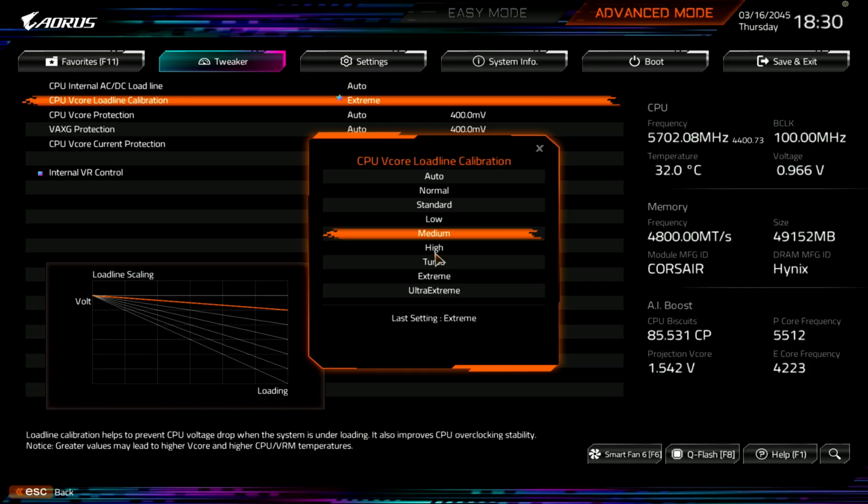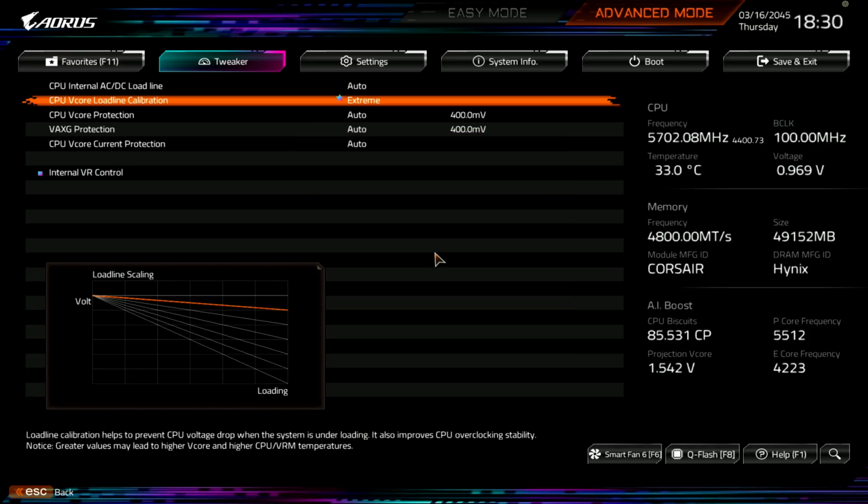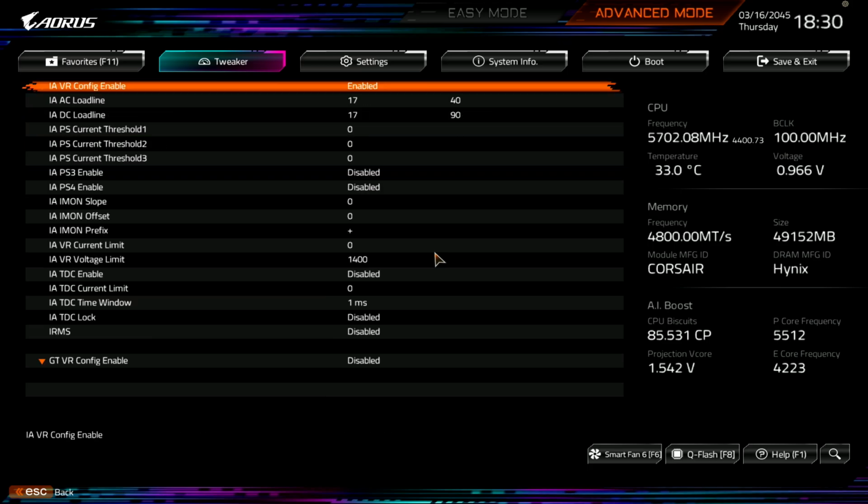You could also just not adjust the load line. That's also completely fine. It's just that adjusting the load line does slightly reduce the starting point for the VID requests, just because of how Intel's AC load line thing works. So you'll get slightly more boost basically, with a reduced load line out of the box.